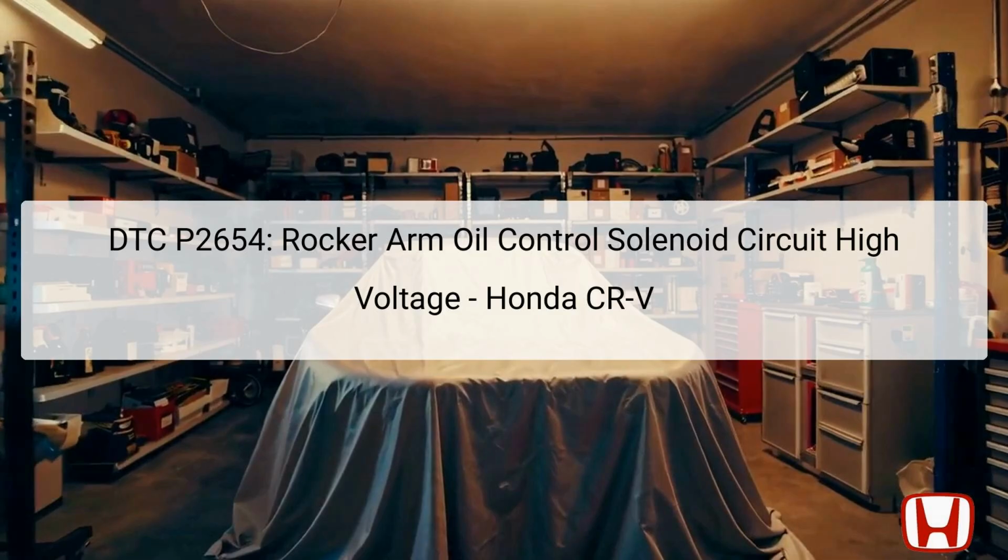When the powertrain control module (PCM) observes an inconsistency, specifically that the rocker arm oil control solenoid return signal is on, while the PCM output remains off, this triggers the error code P2654. This discrepancy flags an abnormality, prompting further troubleshooting to identify the underlying issue impacting vehicle performance and emissions control.